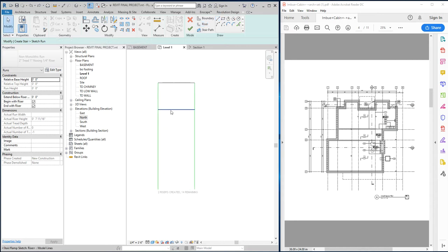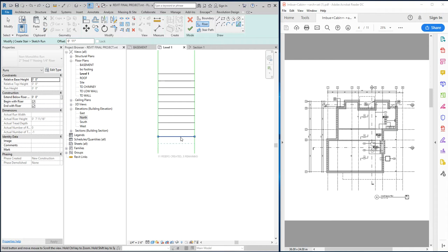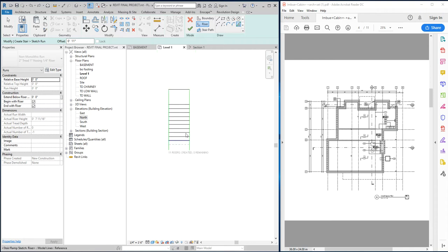So in this case, I'm not going to copy, I'm going to use my riser, I'm going to use my pick. I'm going to give this an 11-inch offset. I'm just going to start creating my risers. And you see as I create them, Revit counts down right here. And if I needed to make a landing in the center, I could do an offset of 3 foot.